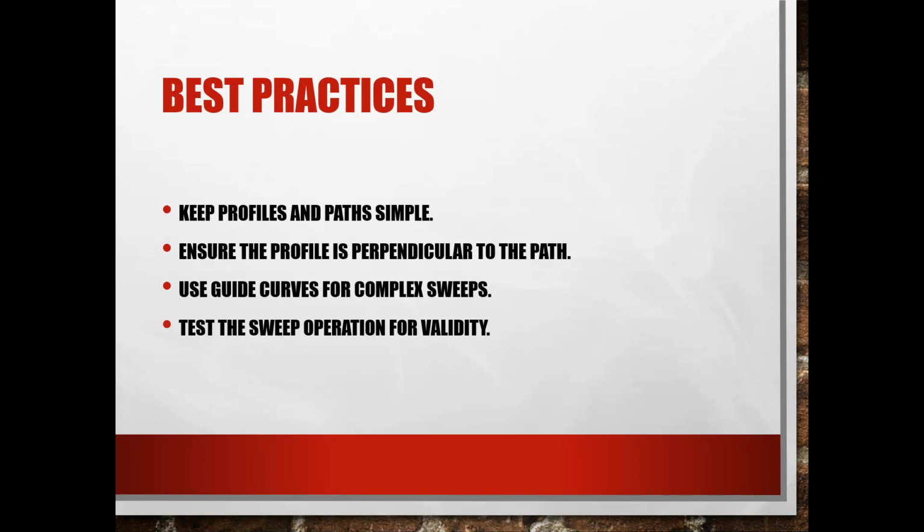All right. If you've got something that's a little bit rough, and I know especially in AutoCAD I tend to use this more than in any other program, there are some guide curves, and that's usually going to stiffen it up. We're going to see this when we do a loft command, and the one that comes to my mind is an example where I did a three-dimensional C-clamp. If you look at that one, you can see that it's a little rough, but you can use some guides and things of that nature to stiffen it up. That tends to be the best way to do that.